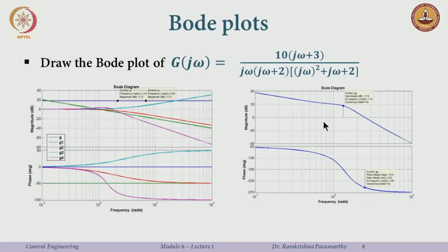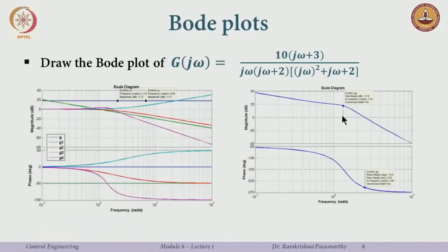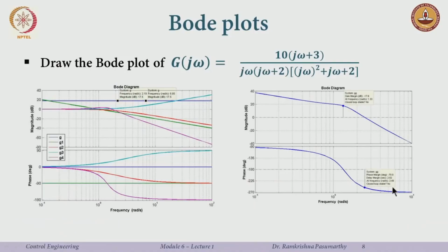Similarly here, if I look at how I defined the gain margin, I look at the point at which my phase becomes 180 and look at how far it is from the point -1 plus j0 in the Nyquist plot. Here it translates to decibels. So, I am looking at this line, and I am also looking at this line for the phase margin, where I hit the -1 point, or where my magnitude becomes unity. Magnitude becoming unity in the log scale would be the 0 dB line. I do all this and it says the closed loop is actually unstable. Okay, what does it mean?